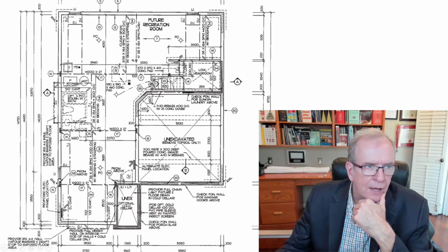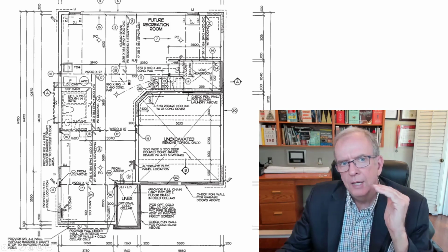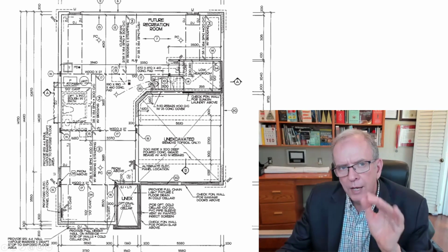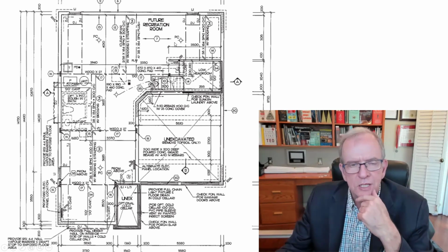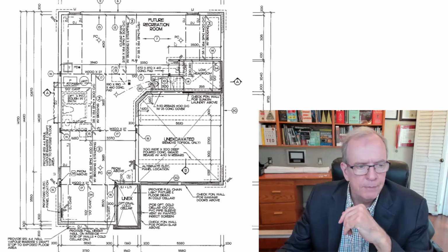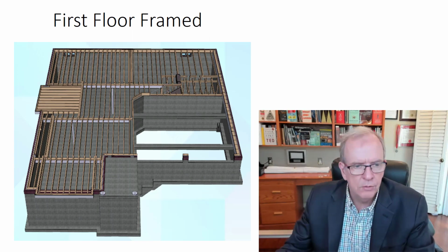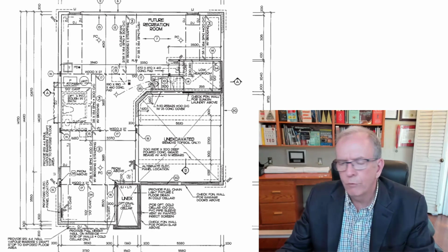We'll talk about the L1. That stands for lintel. In this particular case, we've got a steel lintel that goes on. We've got a unique framing detail that comes here because the first floor is pretty close to grade, and the builder wanted to avoid having window wells. In this example, we'll do other ones with window wells, but there's a unique framing detail that they used on that. And we'll look at that in a future video as well. So hopefully that's getting you a pretty good idea of what we're looking at.